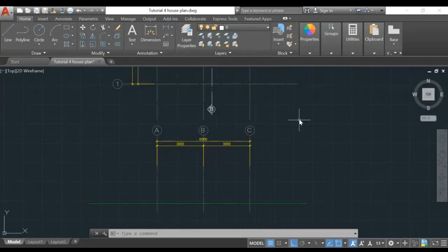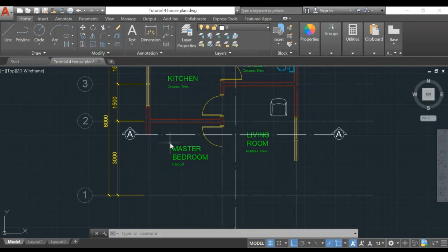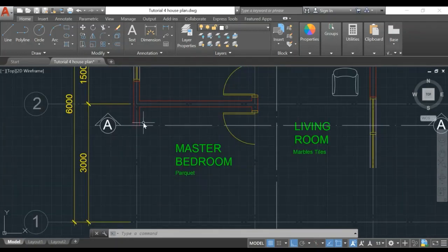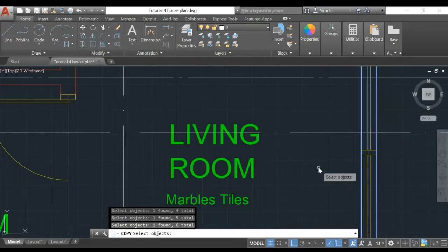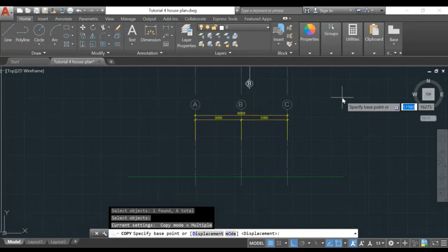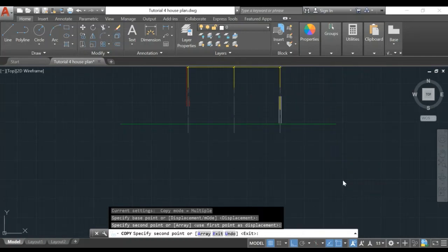All right. So another thing that you need to copy, you can extrude here, is the wall line here. As you can see, right, there is a wall here, and then here on the right side is a window. Right, what can you do? You can just copy the wall line here, and also the window line, press spacebar and push it down. There you go.